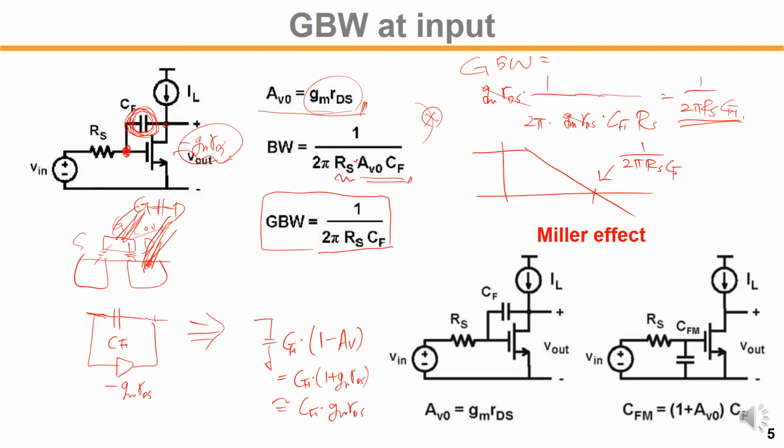So this is a simple example of how we got this. This is the Miller effect. You have to consider the Miller effect to find the equivalent capacitance. Having the Miller effect is critical, especially when you have a negative gain across the capacitor load, because if you apply the test current here, IT. So let me simply derive the Miller effect equation for your reference.